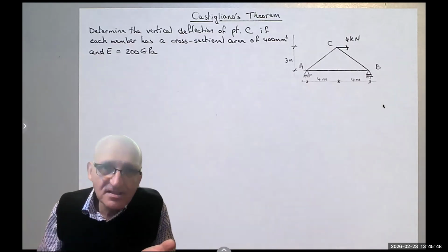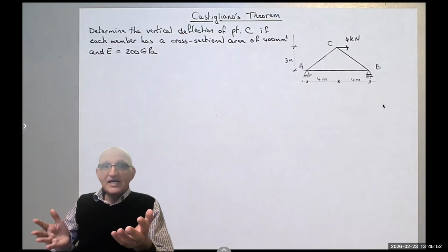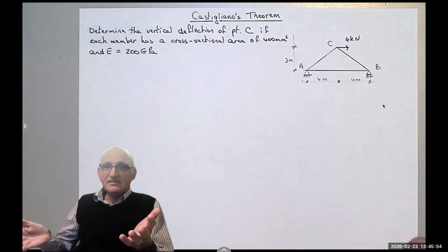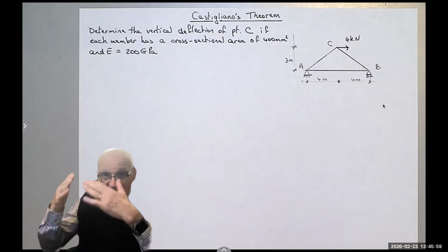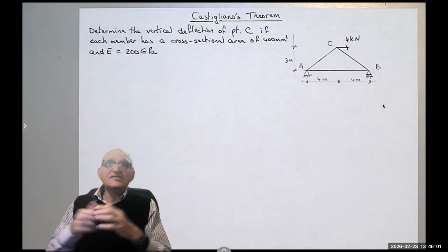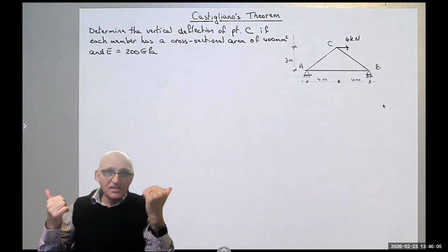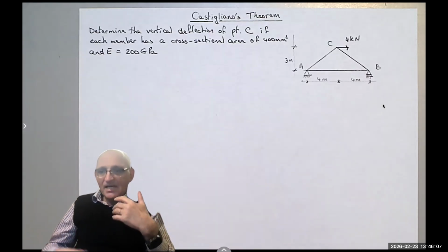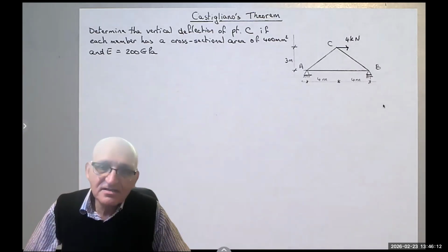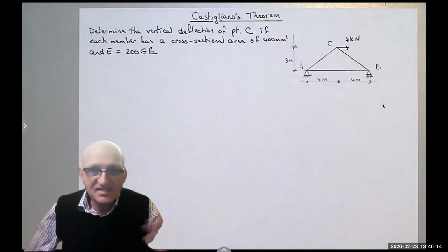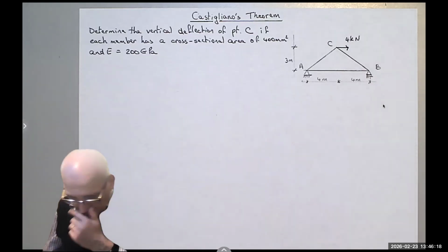Why? You know that trusses are the easiest structures to analyze because all the members there are two force members. So you don't have moments inside members. So it's just axial loads, either compression or tension. That's why it's easy, but then maybe we'll have another session for finding deflections in beams or frames, and you will see it's more involved.